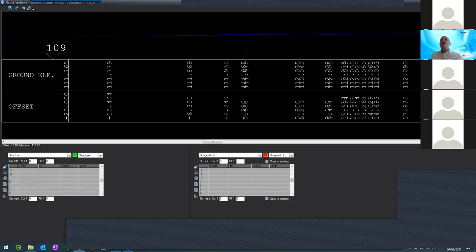So first of all, I'm creating it on section number 0. You see on the right, I'm on section number 0. I'm starting with the structure layer, designing my template. So I'm now on segment 0, offset 0, DH 0. Then, let's say I want to create a 2-lane road to the left, 2-lane to the right. So let's say 3.5 meters each lane, minus 7 meters altogether. This is my first segment, minus 7 meters to the left.